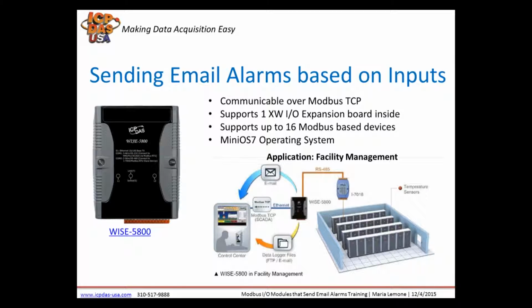Email alarm controllers like WISE 5800 send email alarms based on inputs. Our WISE 5800 is a user-defined I/O and data logger module that can take inputs and trigger outputs from Modbus RTU devices, and is communicable with SCADA systems and is programmable to implement I/O logic. They're widely used in facility management systems for sending temperature-based email alarms to alert personnel about critical changes in temperature, which lead to loss in inventory and production.